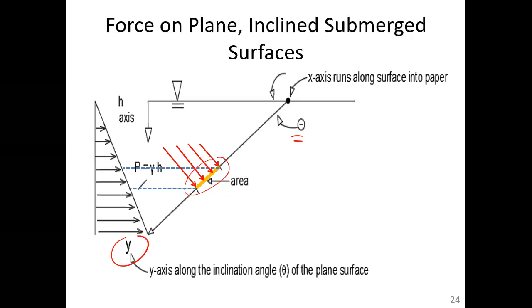And again, pressure is a scalar, so I'm showing it normal to the surface. If we integrate that pressure distribution, we should get some resultant force F. And because we have a non-uniform pressure distribution, that force should not be acting at the center of area.